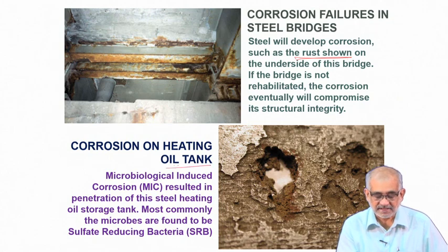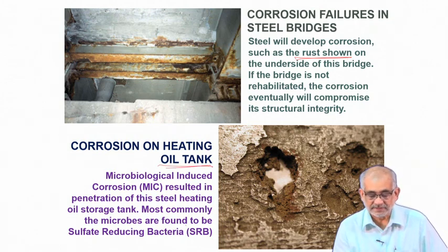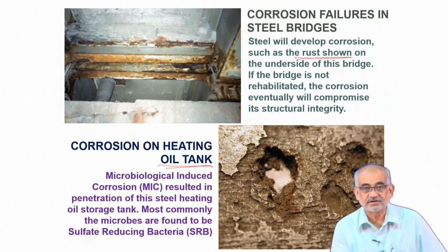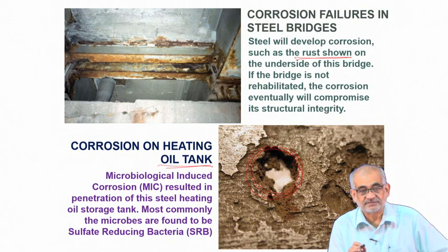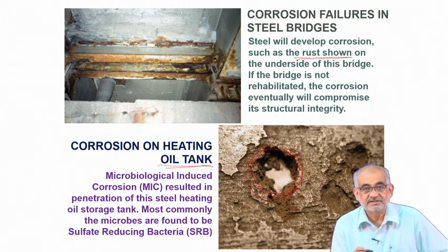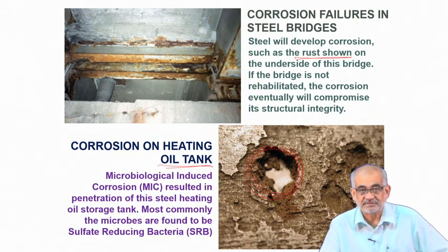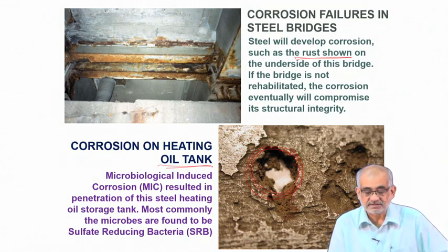So corrosion can also happen in an oil tank. And now you imagine, we always thought that the atmosphere is the culprit, but such severe damage can also happen because of bacteria or microbes which tend to feed on metal. So if you have a portion of a metal which apparently is not revealing much damage because it's immersed under water or some other fluid, in a static condition it may allow bacteria or microbes to grow around the surface.